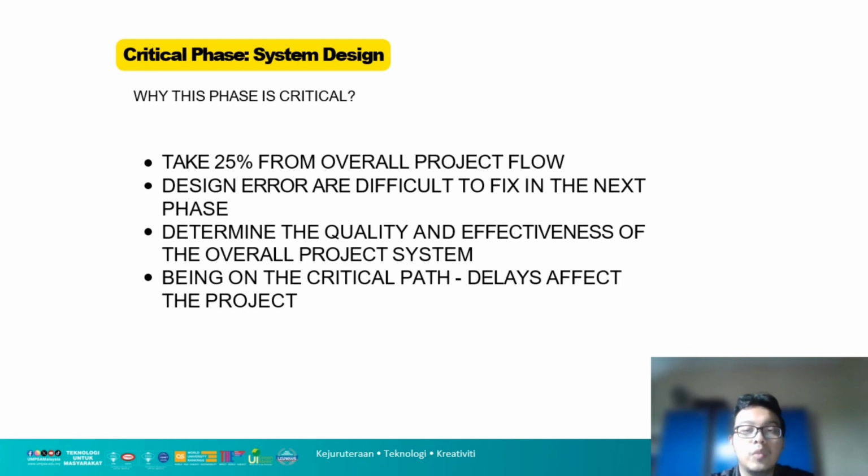During this phase, the team will design the overall monitoring system architecture: select suitable energy meters and sensors for the compressor and chiller system, and design the data communication network using RS485 and internet. This is what the team will be doing at this phase, and this is why I take this as a critical phase. Any design error will affect the installation process and the reliability of energy data, and it will be difficult to correct after installation.